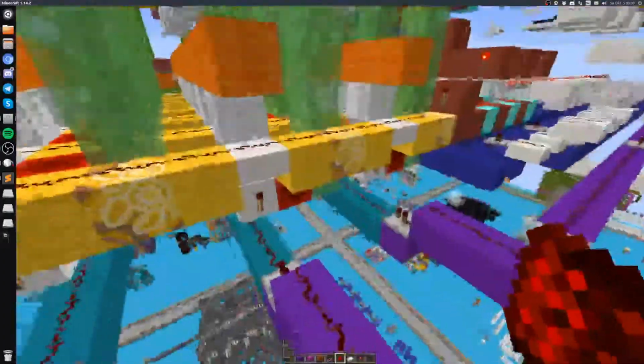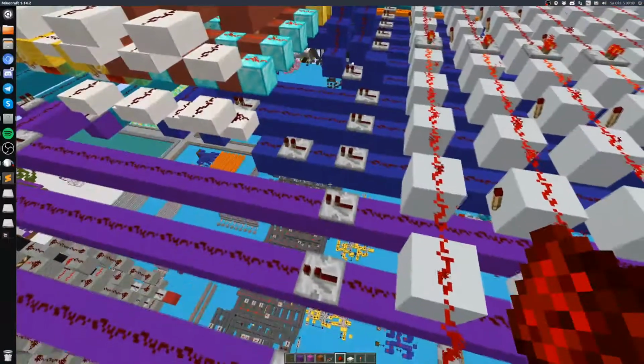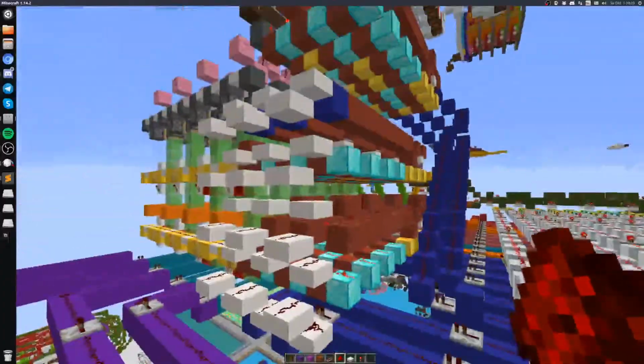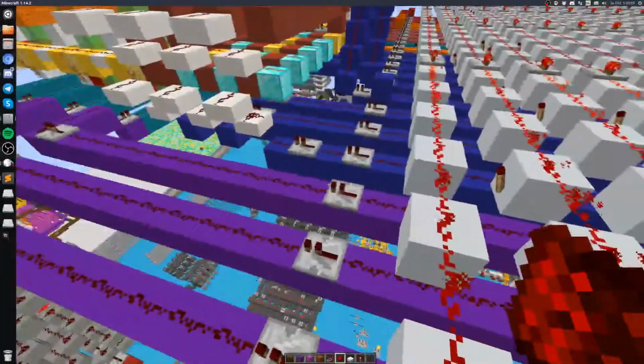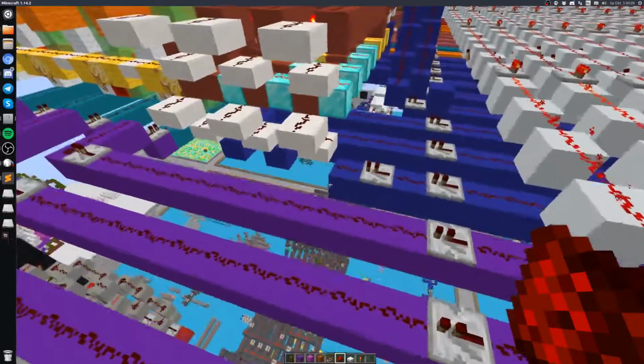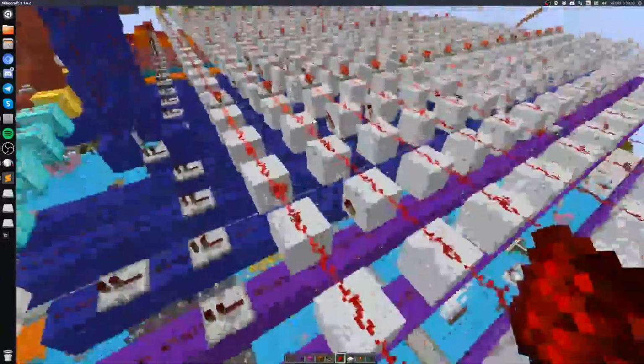We have an 8-bit CPU, but it's okay to use 4-bit immediate because we don't need more. If we implement something like a multiplication, you normally don't want to go over 255 because then you get an overflow, so 15 by 15 is the maximum you can do anyway. So that's also using this part.